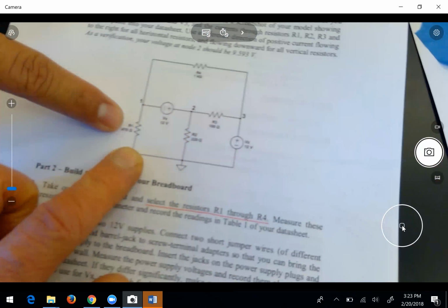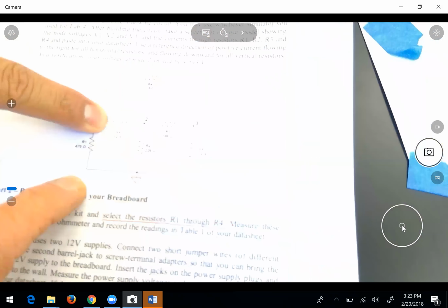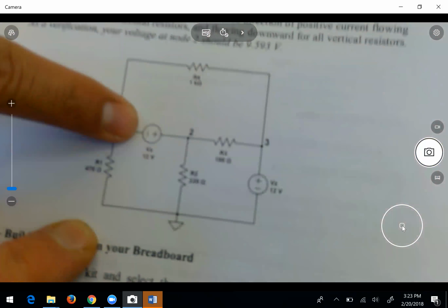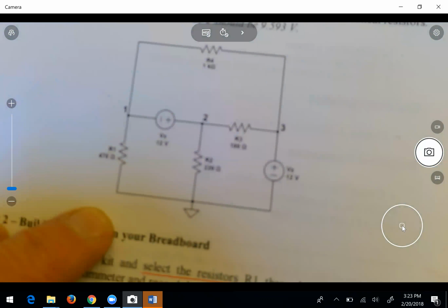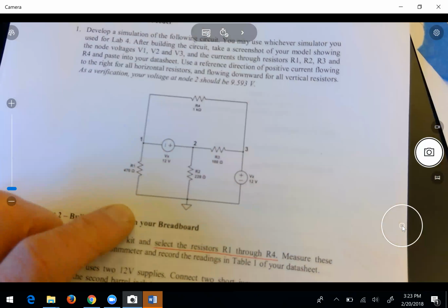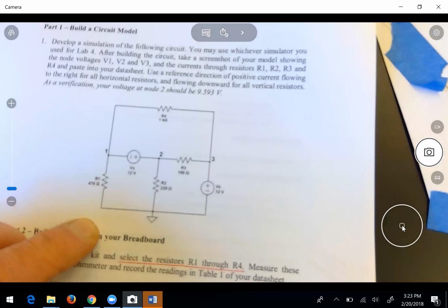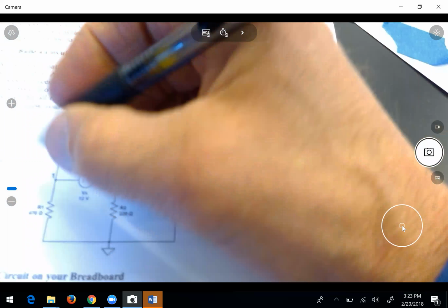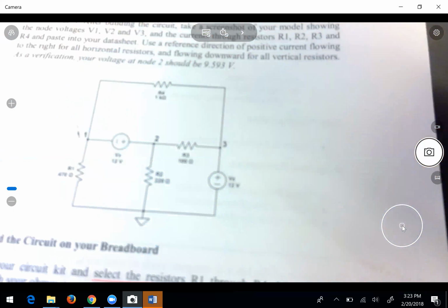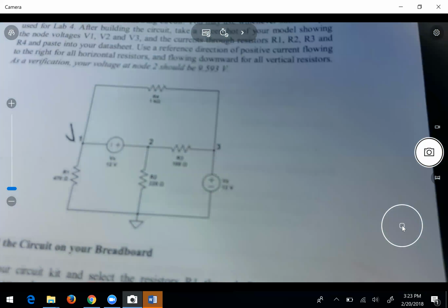So this one's receiving negative voltage, negative 2.4, I think. But it's connected to the ground or to the negative lead of this source, and then to the ground of this source. So it's not necessarily connected to any positive power. So it's still getting power because it's connected to the negative leads, or we're seeing voltage. Yeah, a lot of interesting questions there. How is the resistor getting power given that you have a negative voltage at V1, right? V1 has a voltage of like minus 2.5?